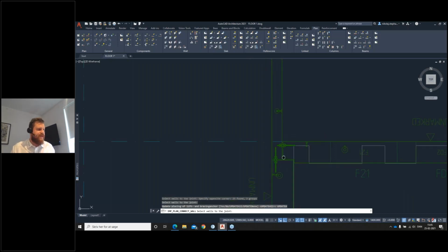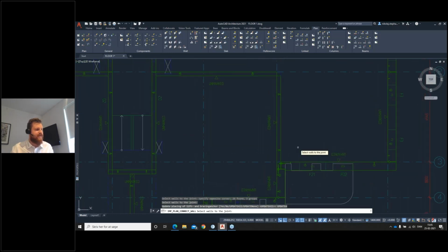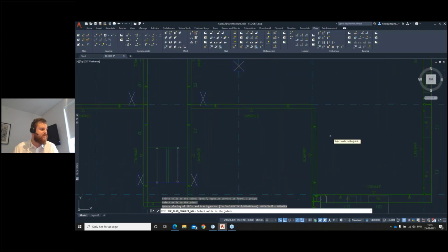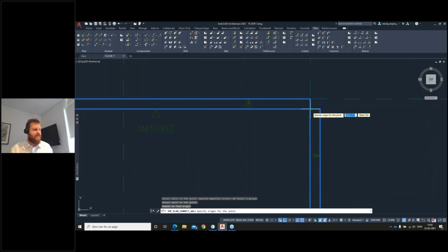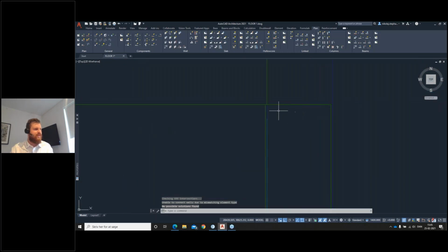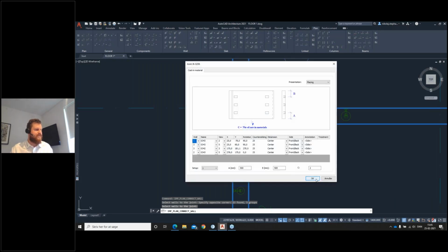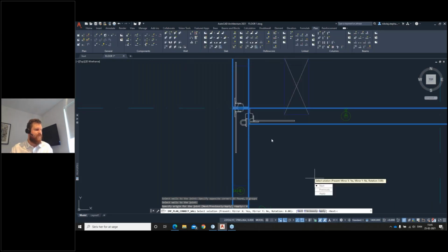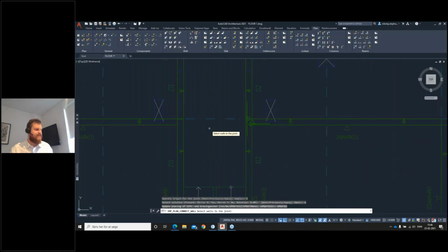So here the same thing where it scans it through, it corrects all the lengths, it makes the indents it's supposed to make, and then it asks me, do you want to join more walls? And of course I want to. So we want to connect, for example, the corners of the walls. We want to connect these here, where we have 3 walls in this case instead. Where do you want it to be? Like this. Now we did the welding plates instead. I'll apply, I'll click update all. We got that connection instead.